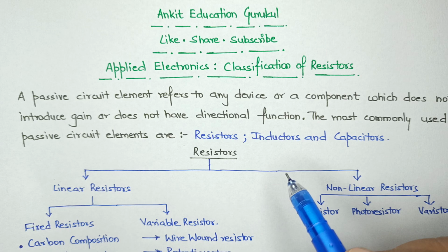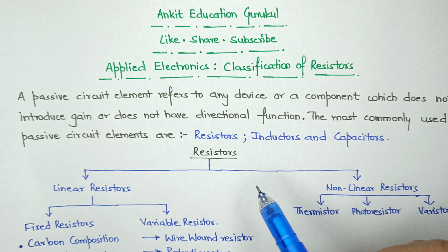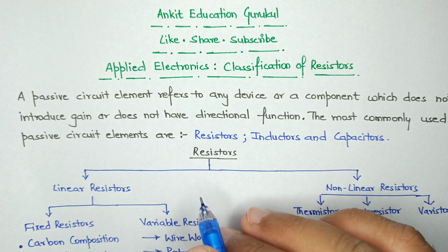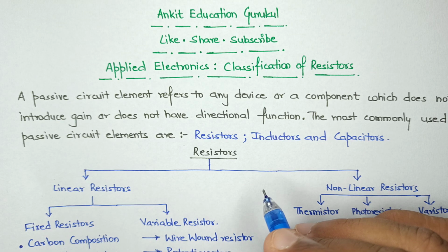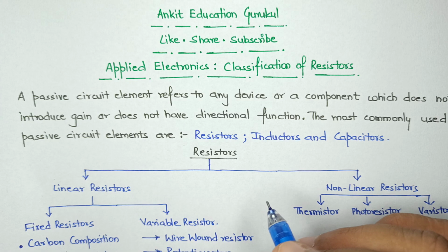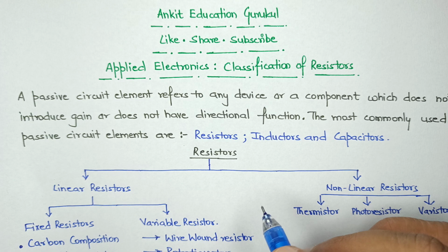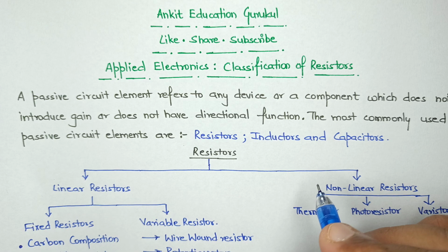The thermal stability of a resistor is indicated by the temperature coefficient specification, which is usually expressed in parts per million per degree centigrade. A smaller value of the temperature coefficient will have less variation in the resistance value, and therefore a smaller temperature coefficient means a higher thermal stability of a resistor.